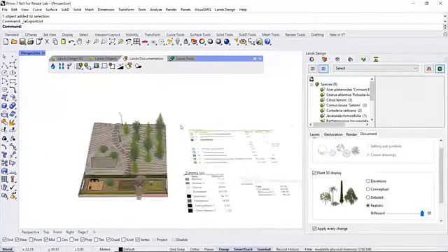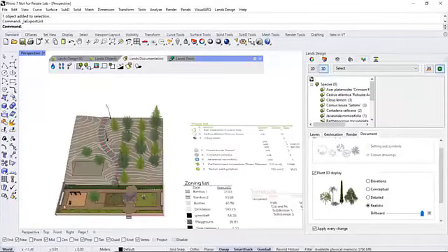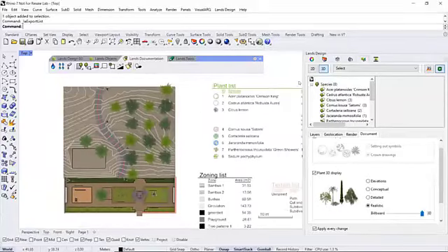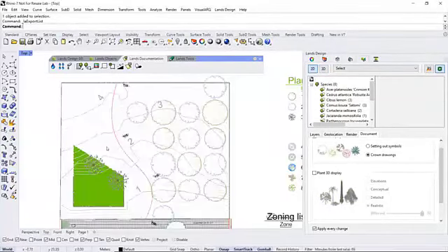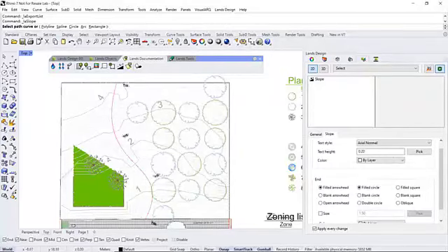All right, so let's see some other features for 2D documentation. Maybe we can measure the slope on this terrain using this slope tool. Basically, this calculates the slope between 2 points, from the start and end point that are projected on top of the terrain.